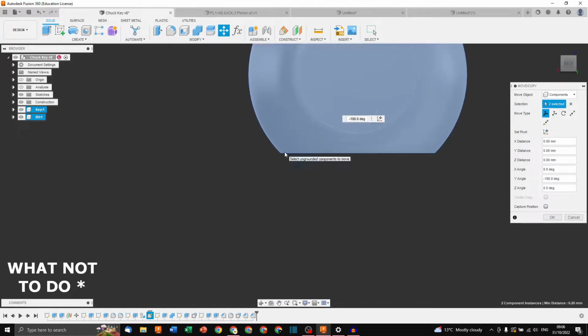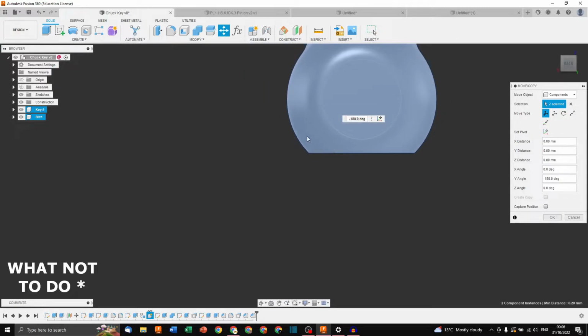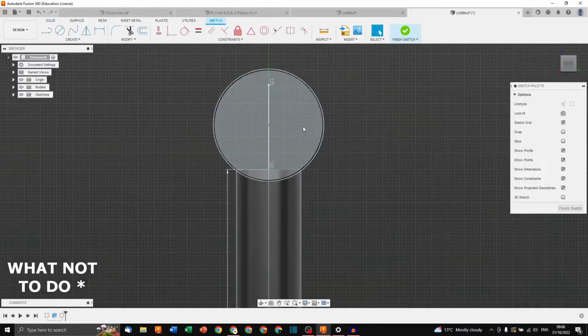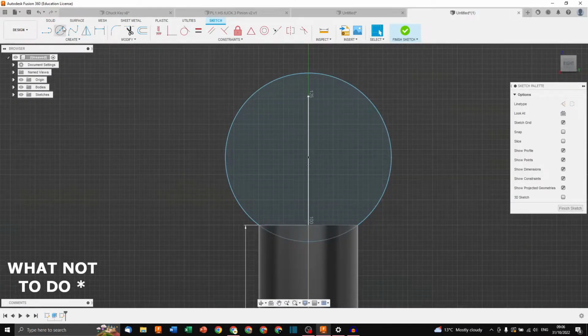So I'd like to have less than 45 degrees here, because if I have 90 degrees, like if I print the whole circle, well, my printer is going to slop down here because the plastic will be printing in thin air. So let's chop off the top of that one.